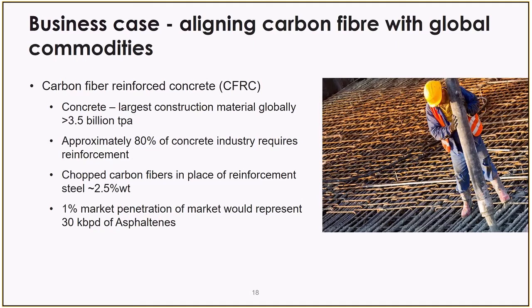People have heard the phrase rebar, reinforcement bar, steel bar. Now consider chopped carbon fibers, or short strand carbon fibers, in place of reinforcement steel. This is something that's emerging pretty quickly. At a weight of about 2.5%, that is to say, a chopped carbon fiber could be a few centimeters in length at the thickness Axel was alluding to earlier. This is mixed in with the concrete, and that is applied in place of steel reinforcement.